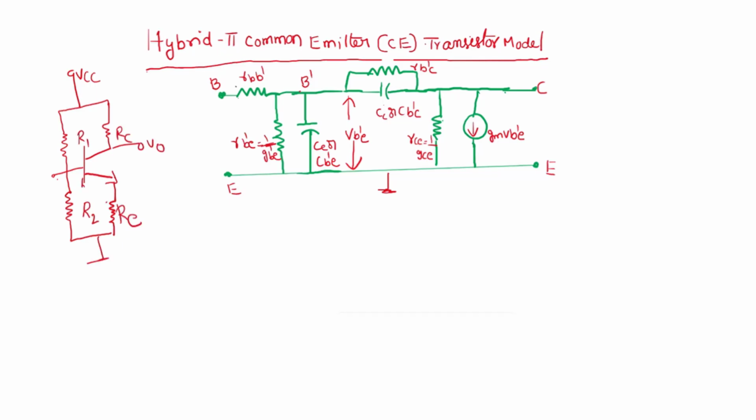At high frequencies, all the capacitors get shorted. Input capacitor CB, that is a blocking capacitor, the output coupling capacitor, and the emitter bypass capacitor. If all these get shorted, then RE becomes short. And as this is short, yes, you have a supply here. So now here you have another short.